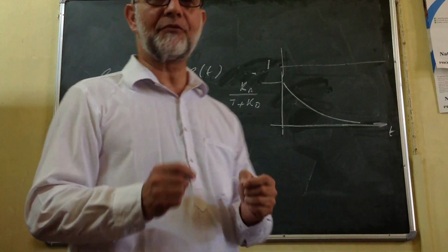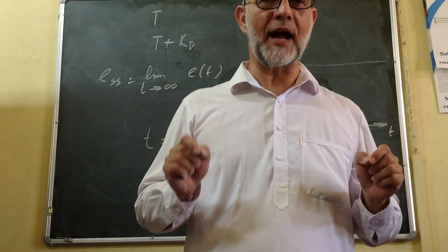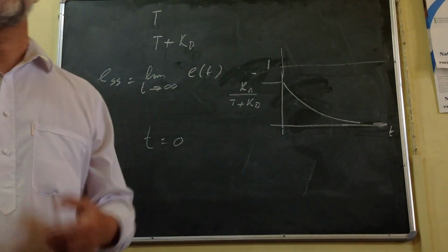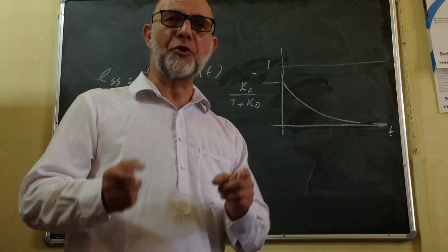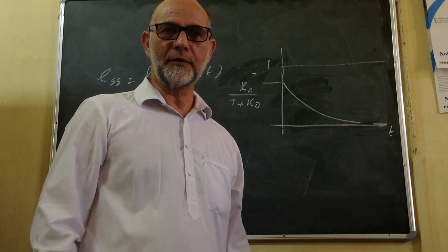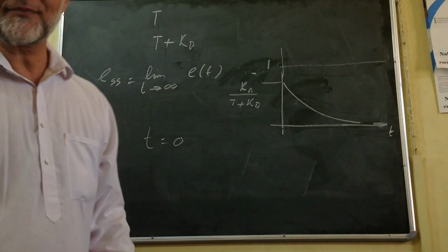Hence, a derivative controller is never used alone in actual practice. You will always have it in combination with a proportional controller, or as a combination in proportional plus integral control. Okay, so I think that's it.